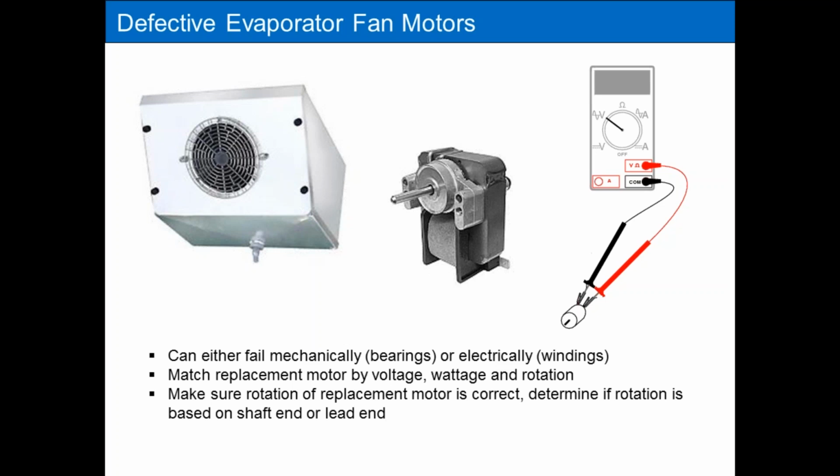Verify it. Make sure you have voltage going to the fan first, and if you have voltage going to the fan and it's not spinning, change the fan. So that's a pretty simple tell.